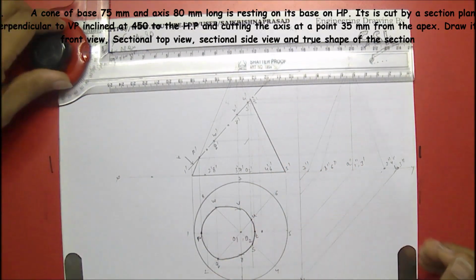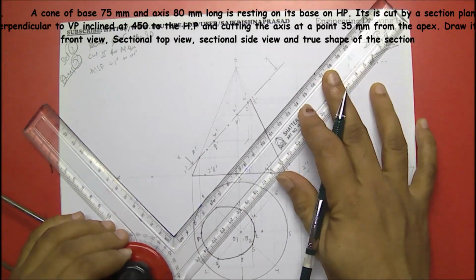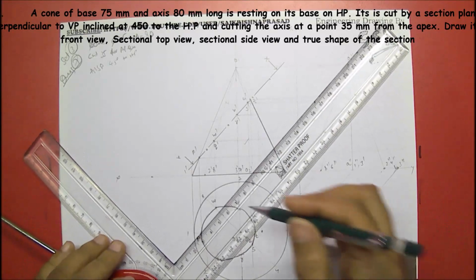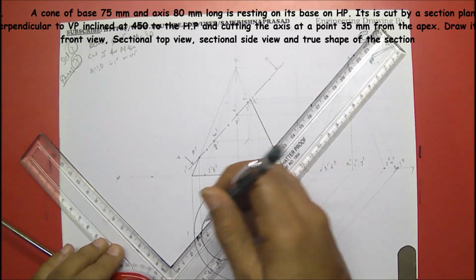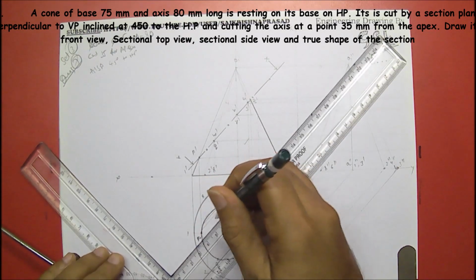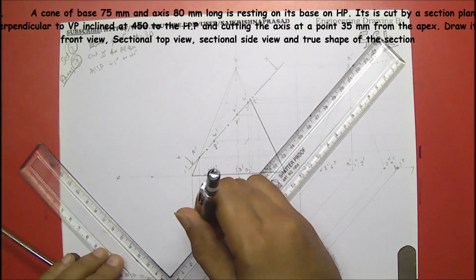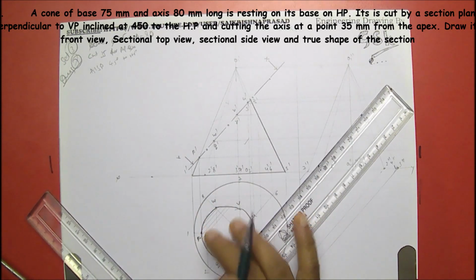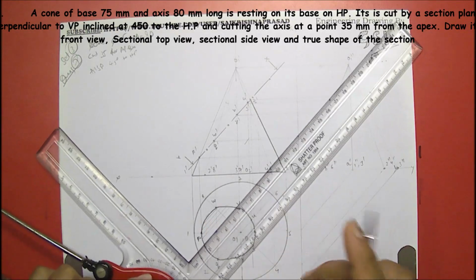Right, this is section 1. So for section 1, we have to represent it with the hatching lines. Thin dark lines at 45 degrees, and 2 mm or 2 to 3 mm can be the gap. This is thin dark and 45 degrees line with the gap of 2 to 3 mm.